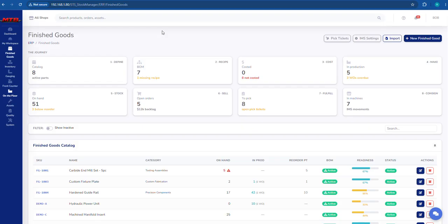This also lets you put drawings in. Currently today we're working on a way to actually drop in a model and click the features you want inspected at the machine with the cycles you want it to be inspected at, and then the guy actually touches each feature at the machine at that time frame, and then he enters his numbers against the drawing. So as an example, if you had 4 holes, you actually push the picture of the hole on your screen, it'll pop up, and then it'll drop down a little thing that says what are you getting for an inspection reading right now, and then you drop that in, it'll tell you if it's conforming or non-conforming to what the preset dimension should be. So it's kind of a cool feature for inspection at the machine as well,